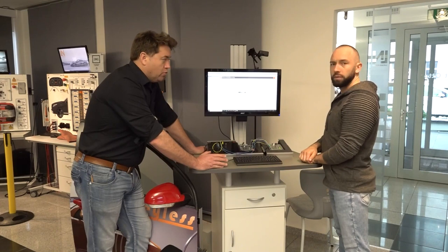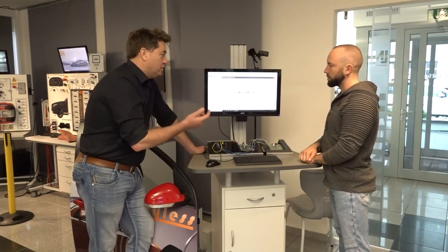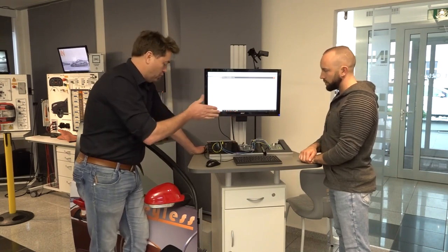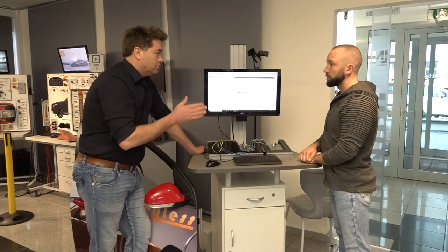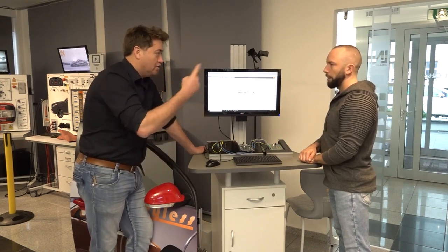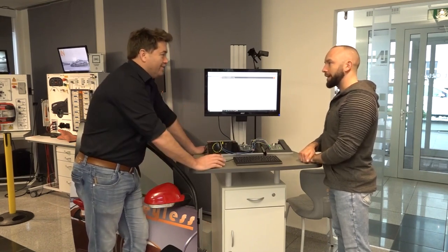Obviously that's the old school way, is having a switch going through to an actuator, which is then 1 for 1. One switch is available for 1 action. So you can imagine the mirrors on your vehicle, so going up, down, left, right. You need 4 switches and 4 cables just to activate, and then the return of that as well. That is how it was back in the day.